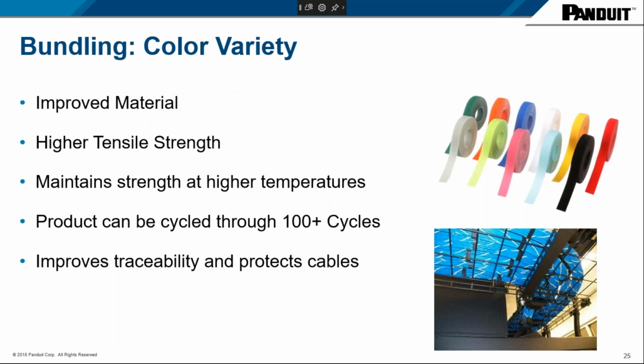And here I wanted to move into, quickly before we end, the importance of bundling. Especially when you're putting product into a wire mesh basket, when there's a lot of cutting involved, you want to make sure that you're bundling the cable. By bundling the cable, you're able to provide a larger diameter cable, in the sense that it does provide that protection, and you're also able to maintain it and push it away from any sharp edge or burr.